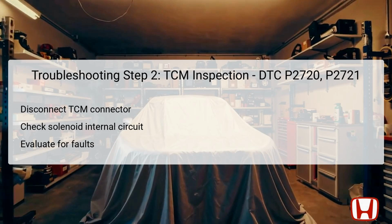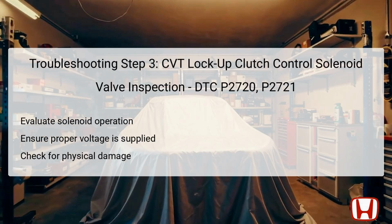This step is critical as it ensures that the control logic of the transmission is intact and capable of accurately commanding the solenoid valve during operation. Should the TCM check out fine, additional diagnostics on the CVT lockup clutch control solenoid will be essential to ascertain the root cause of the DTCs. The final troubleshooting step focuses on inspecting the CVT lockup clutch control solenoid valve itself.